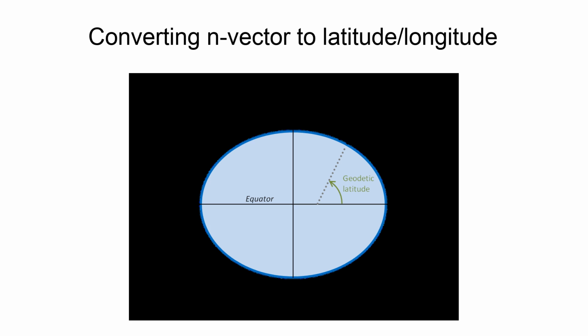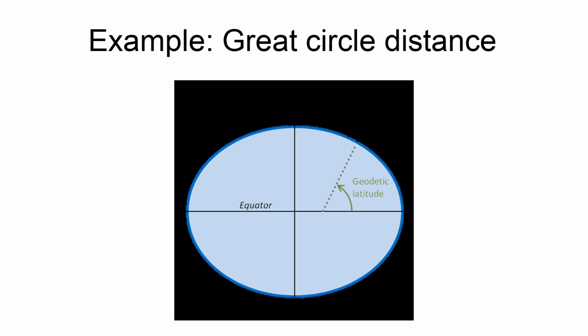Finding the great circle distance between two horizontal positions, assuming spherical Earth, is usually done by means of latitude and longitude. Three different expressions for this distance are common. The first is based on arccos, the second is based on arcsin, and the final is based on arctan. The expressions, which are successively more complex to avoid numerical instabilities, are not easy to find, and since they are based on latitude and longitude, the pole singularities may become a problem. They also contain deltas of latitude and longitude, which in general should be used with care near the plus or minus 180-degree meridian and the poles.